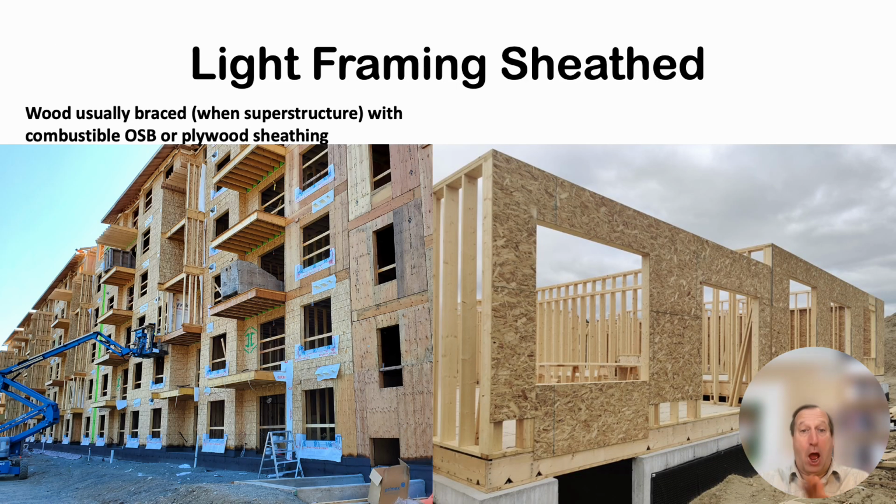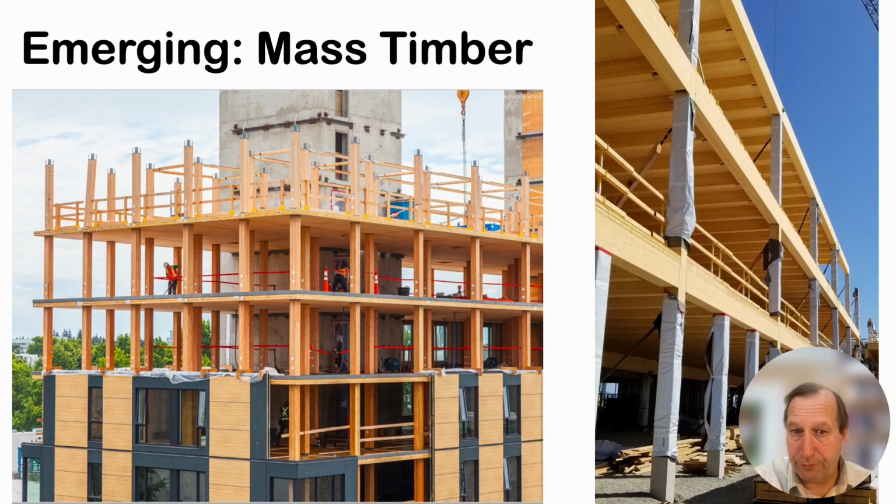This is done a lot, and it allows us to build 4, 5, even 6-story wood frame buildings using standard sized wood, light wood, and standard thickness sheathing. That will get you to 3 stories. And then with a few closer spacings and a bit of engineering to pick up the higher loads, you can get to 5 and 6 stories. Now, that's light wood framing. Really, there's very little difference structurally between a hot-rolled steel with braces and a mass timber as we're seeing today.